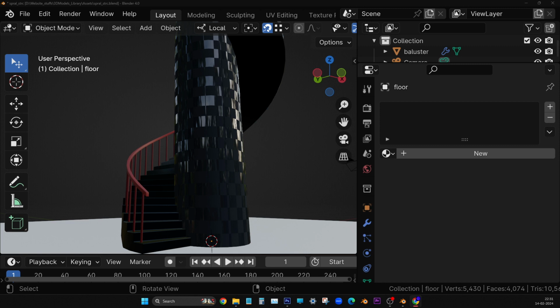checker. So for how to get there, Shift A. This way also you can go, but Shift A is the shortcut. Yeah, checker texture. It will come actually. Just move the cursor. Now you have to connect it to base color first initially, then you can connect it to roughness. Now it is showing some pattern. Maybe you can zoom out a little and pan it down. Okay, fine, nice.